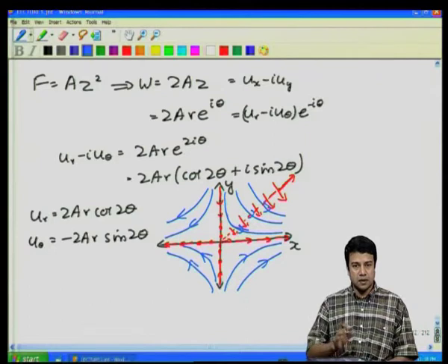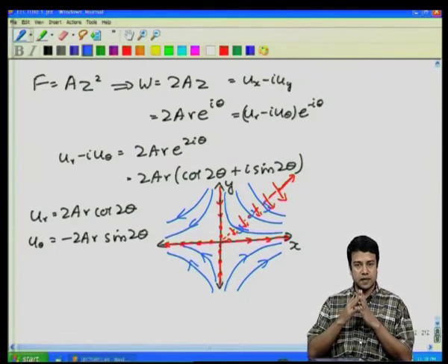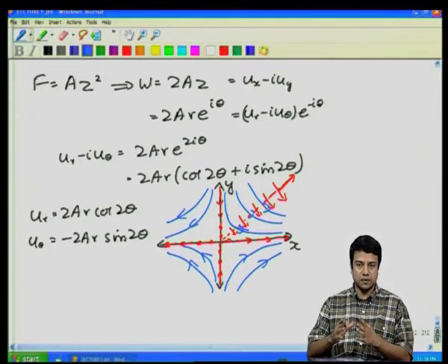So, I said that this represents some potential flow which satisfies the known normal velocity boundary conditions at the bounding surfaces. One can turn the argument around and say that the bounding surfaces are those surfaces along which the normal velocity is equal to 0. For this particular flow, valid boundary surfaces are those surfaces for which the normal velocity perpendicular to that surface is equal to 0.